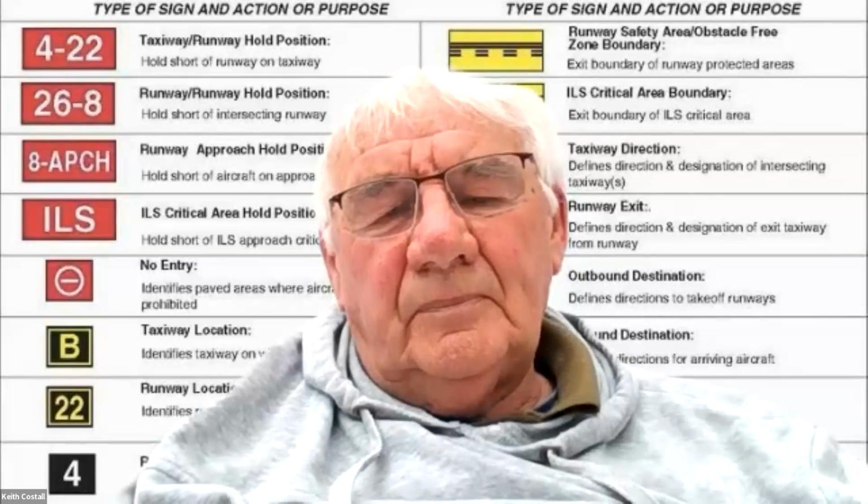Okay. And so we're now pushing the photometric testing. And it's a hard push with them. Within the last year, an FAA certification inspector landed at a major airport, came in and said, we're going to test your lights. You have 5 steps of brightness on your lights. Let me see if they're working properly. So the maintenance person just controls his regulator. He goes through all 5 steps, all the lights are on. He said, okay, you're fine. That's it. No indication of getting out and doing the photometric testing.